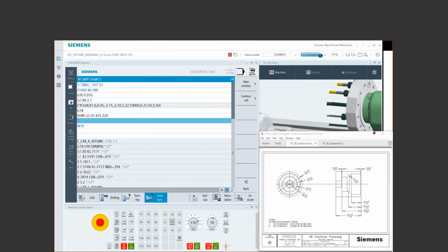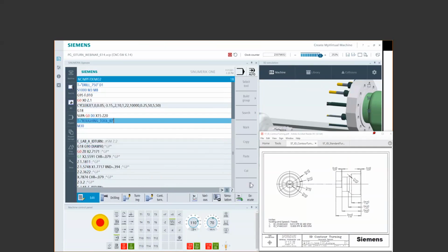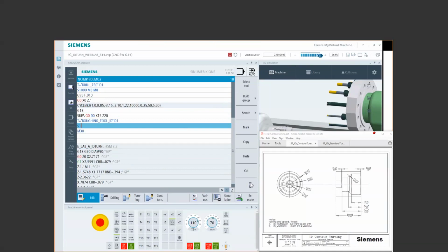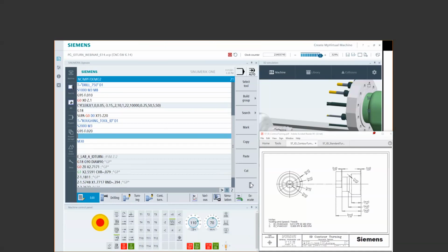So let's go grab our ID turning tool, like we used before. I'm going to grab this ID turning, pull up the appropriate cutting edge, D1, make sure my spindle is running at some RPM, some speed, and my feed rate, F. I am going to probably preposition. That'd be a good habit to get into because I did just drill a hole. So I can send the tool to an X of 0.750 or 740, right around the hole size, Z just off the part.